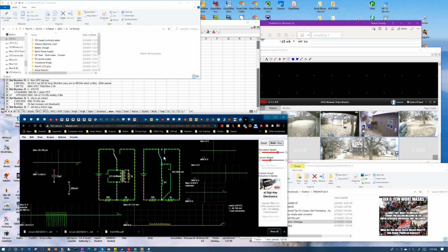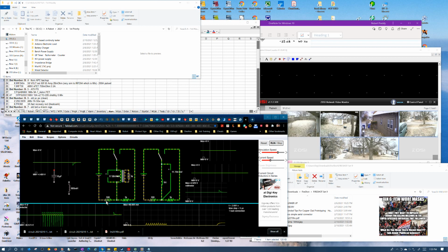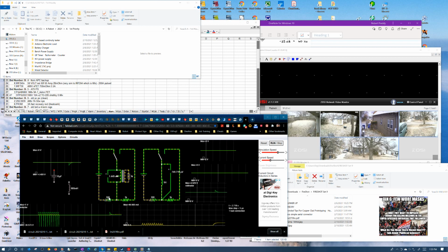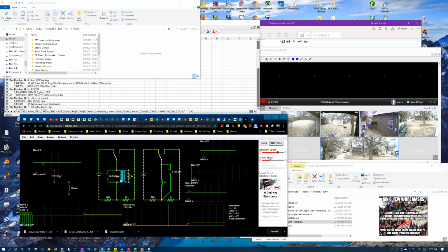So now the fields will charge up much more quickly, but we're storing 1/100th the amount of energy in the coil, so that's why it actually charges up more rapidly, even though we made the resistor larger. So you would think it would take longer to charge, but in fact you're storing less energy in it because you made that larger. Remember, in the end, the voltage across these coils is still the same 0 volts.